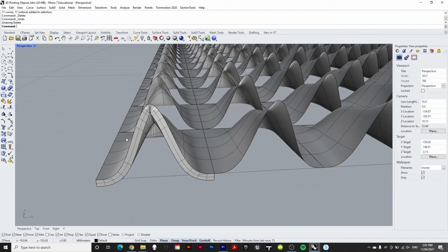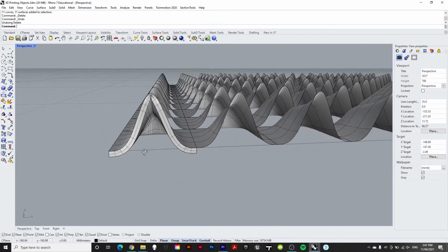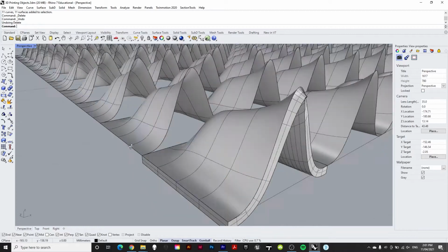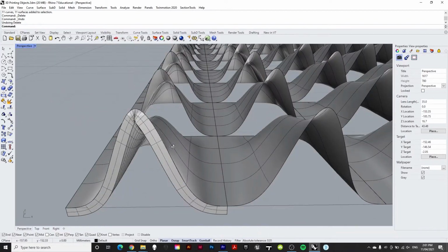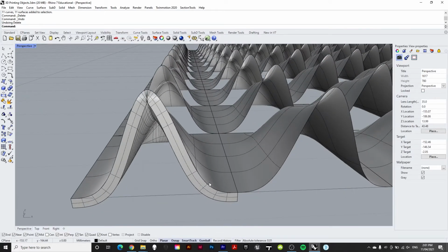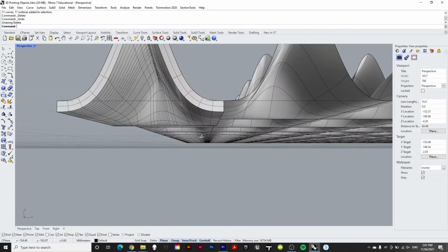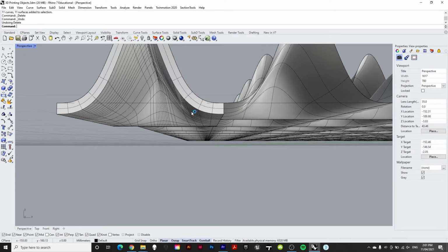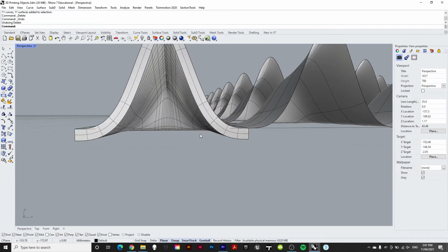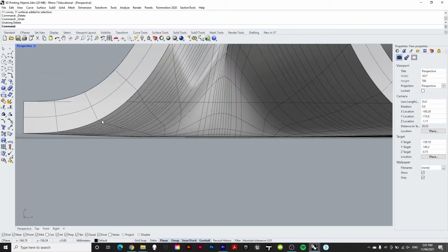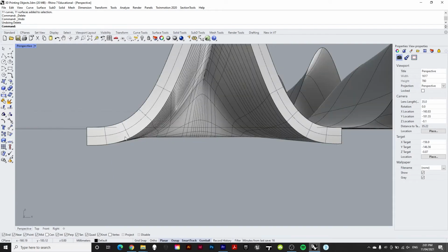Now obviously you need to ask your fabricator what they're doing, but if you are using FDM with PLA, this sort of geometry is going to become a problem. It will start off fine down here and be able to go all the way around. It's pretty flat around there, but you'll see as we get to these points here, we do have no material touching the ground. So if this is our flat plane down here, we're going to end up with the 3D printer trying to print geometry on top of air. So that is going to cause an issue for us.